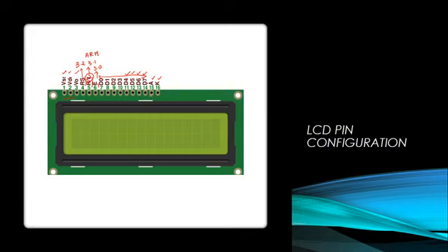Similarly, the 4 data pins have to be interfaced to the ARM processor. They are pins 2.6, 2.7, 2.8 and 2.9. These pins are internally configured for the LCD. So when we mention the header file lcd.h, these connections are also defined there. So we have to give the same connections as I told here. We cannot interchange the connections, and we cannot change the pin numbers. So it is 3.2, 3.1 and 3.0 for register select, read/write and enable, and 2.6, 2.7, 2.8 and 2.9 for D4, D5, D6 and D7.